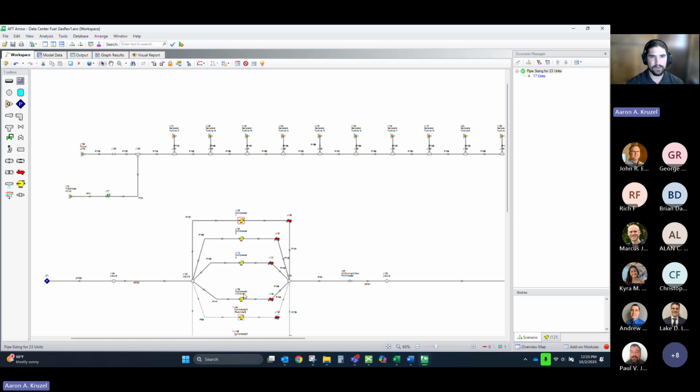So being accurate with your retrofits, making sure everything, one, fits for sizing, but then making sure the pipe can actually handle it. So let's say you add another compressor. Sure, you have the theoretical ability and it has the rated ability to shoot out a couple thousand SCFM of natural gas, but what if the pipe can't handle it? Being able to model that gives you visibility and a very clear understanding of what your system is able to do.